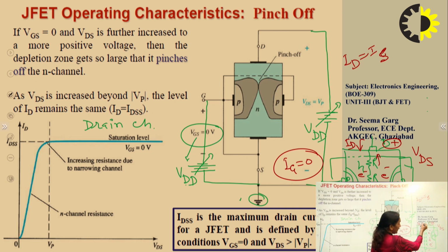Now, as the current is flowing in the circuit, if you look at this point, the voltage V1 will be equal to I into R. If you measure the voltage at this point, because the resistance gets added, the voltage V2 will be equal to I into 2R. Here it will be I into 3R, and so on.